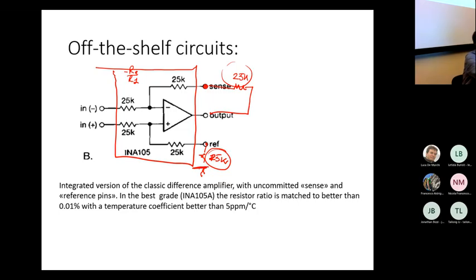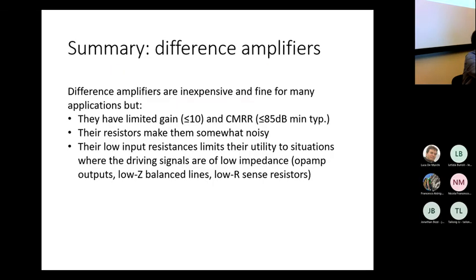Okay, so how can we cope with the limitation of the difference amplifier? These guys are relatively inexpensive, but they indeed have a limited gain because typically it's difficult to have a very good matching at different scales. So we typically select, when we buy this component, with just slight differences between what we have called R1 and R2.